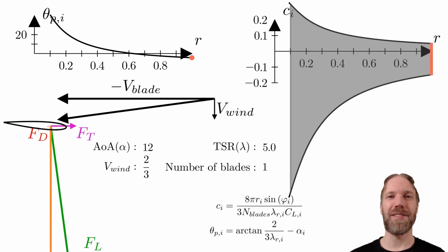We can also look at the one-bladed solution. It should be obvious that the optimal chord is only theoretical and that it's not realistic to build a turbine with this large chord. The normal approach is to deviate from the optimal chord for low radius to reduce the mass and size of the blade.